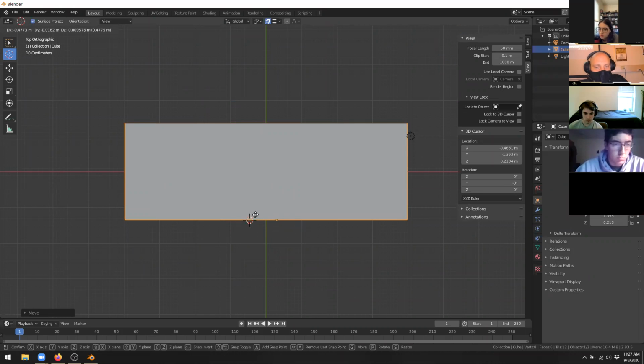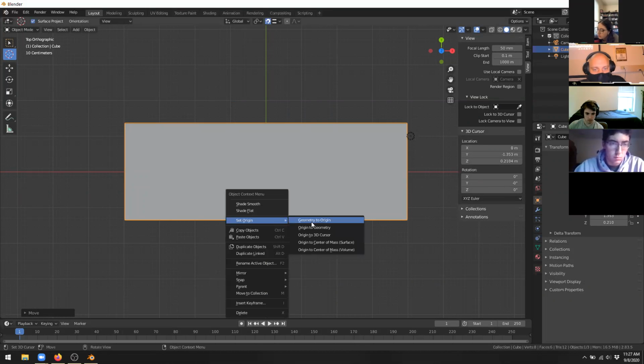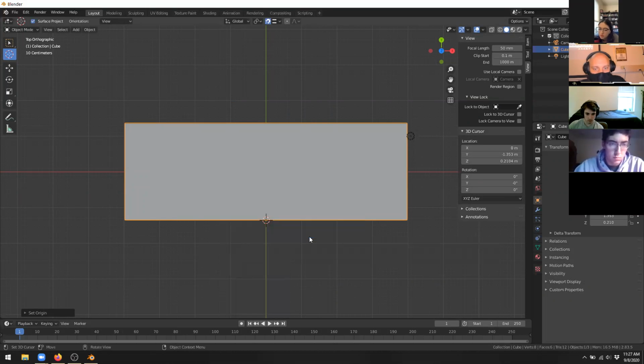If we look over on the side, it's changing my X value. If I get close-ish, I could tell that 0 is that start point. And what I could do is just manually set my 3D cursor to 0, which means it is going to be centered. And then once I've done that, if I go in and set my origin to the 3D cursor again, it should get me right on the edge and right in the center of my object.